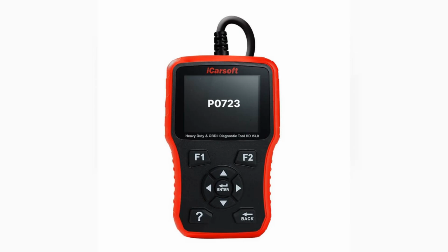The speedometer or tachometer is not working, or is faulty. Gear changes are difficult. Problems shifting gears. The engine does not accelerate well. Jerky or false ignition at idle or under load. The engine may stall or not start. Reduced engine power. Increased fuel consumption. Error P0723 is quite serious, as the conditions that lead to its persistence can cause damage to the transmission.